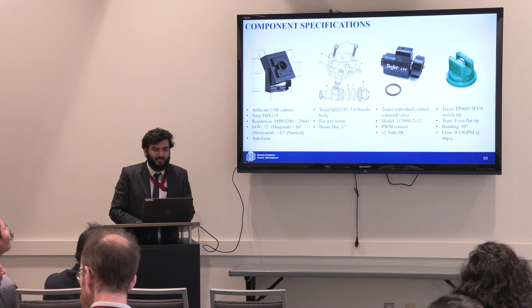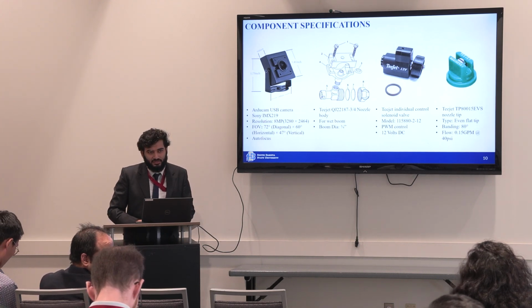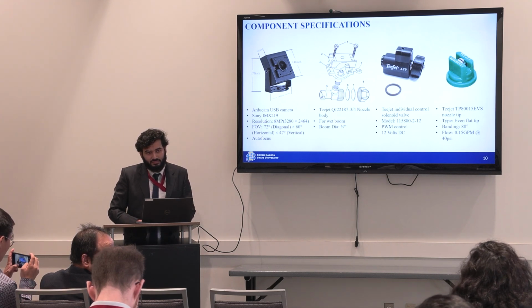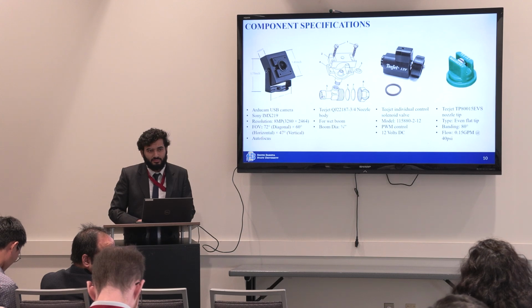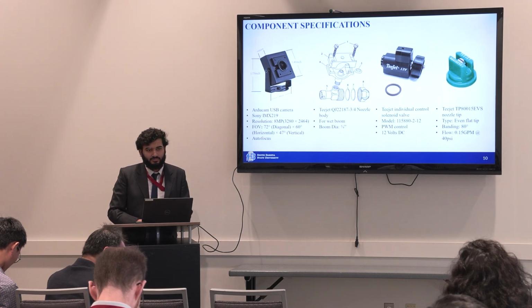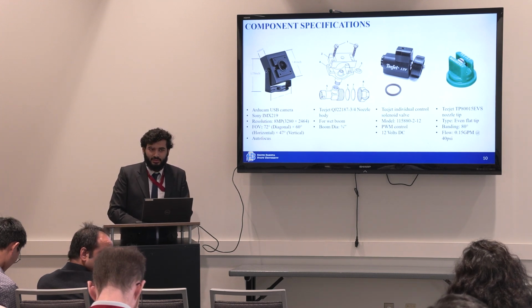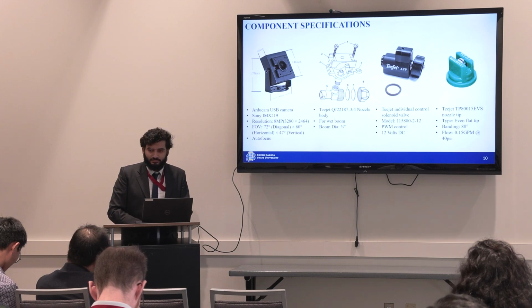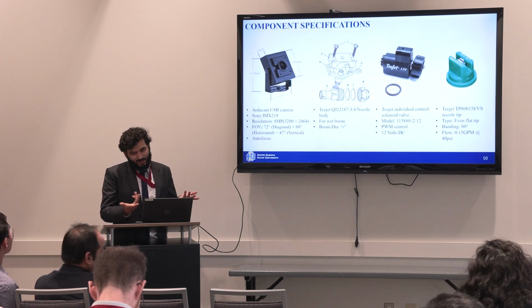One thing, we are also working with Jetson AGX, and we tried to utilize the GPIO pins to control the actuators and other stuff. But what we found out is that the GPIO pins work as input, but cannot submit the commands to the motors and other stuff. We contacted NVIDIA as well, but they did not give us a proper solution for that. So Arduino might work.